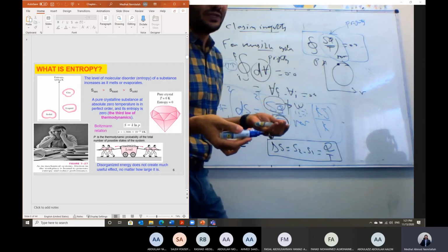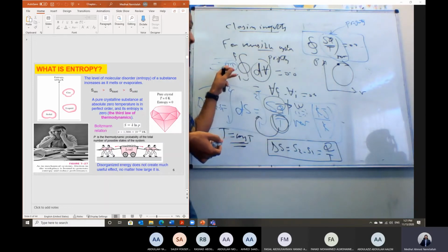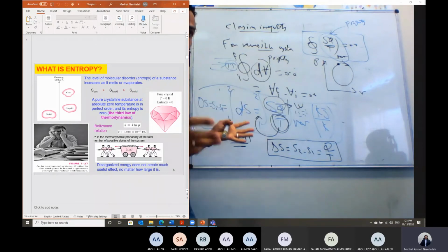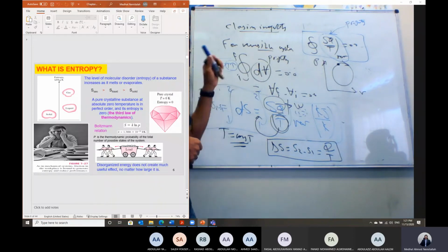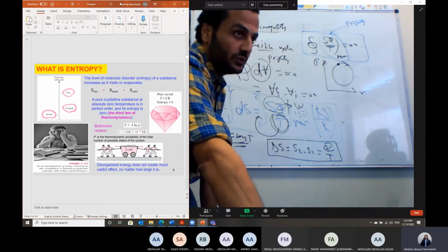Otherwise, we could not have any losses within the system. If the losses within the system, like the friction losses, were converted to heat, then we could convert this heat into work, so we wouldn't have any kind of losses. But this heat is not available to be converted to work. It is just dissipated in the kinetic motion of the molecules. And that's why, when I calculate the entropy generation within a system, it is a direct measure of the losses within this system, because at the end, the losses within the system will be dissipated in the kinetic motion of the molecules. Okay?